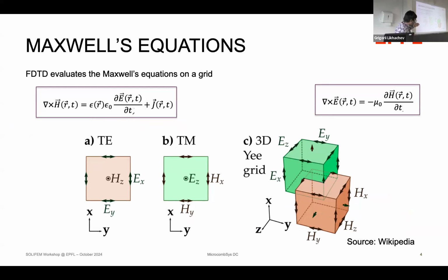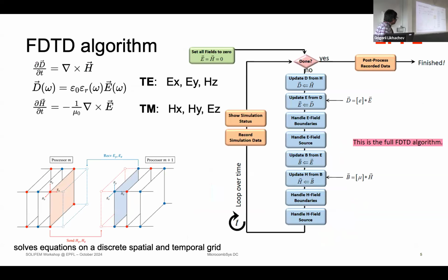But then when you discretize your system, the algorithm behind FDTD solves it. First, it divides your system into a set of E grid cells, they call it. It would solve the first equation in one of the grid cells, for example, the green one that's shown here. And there is the adjacent E cell, whose corner lies on the center of this E grid cell. It will solve the second equation. And then it will feed this back to the magnetic field equation, the cross product between the magnetic field equation, and then it would continue this, and then the light is going to propagate along the entire length of your device. So that is what is shown over here.